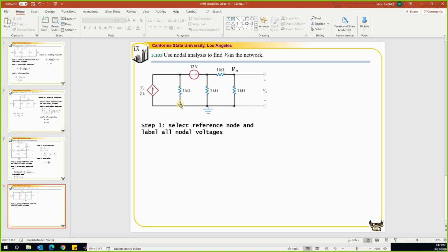This is one node. Although it's labeled as a dot in the circuit diagram, this is one node. There is no element between these two dots. This is simply just a wire. This is one node, so it doesn't matter where I put it. I can put it there as well. It's the same. It's considered a supernode, correct? That's why we could consider all three of those dots the same node. So this one is not a supernode because this is just one node.